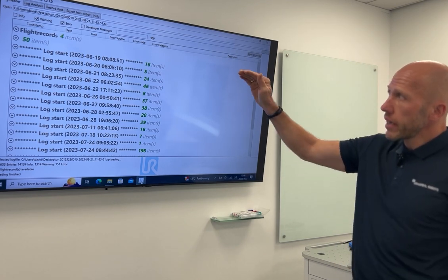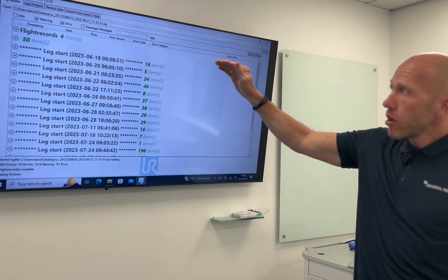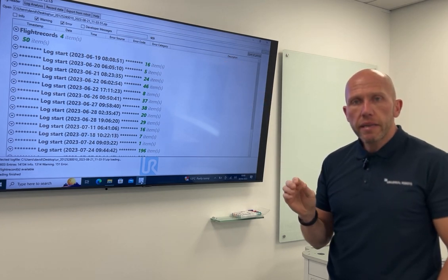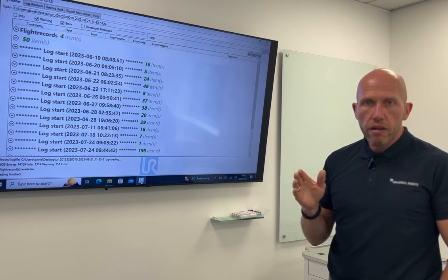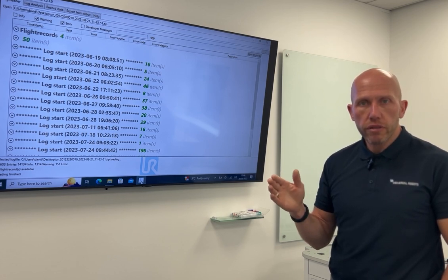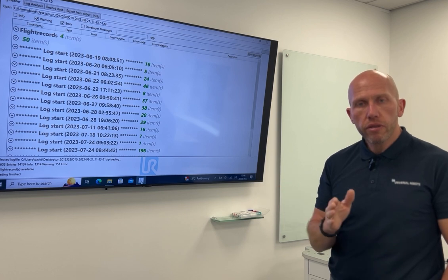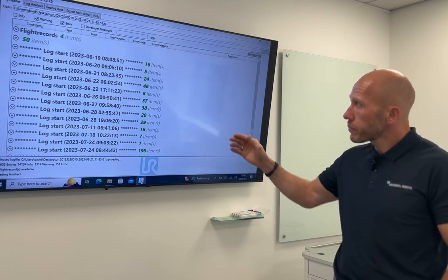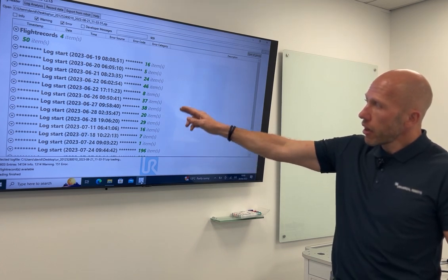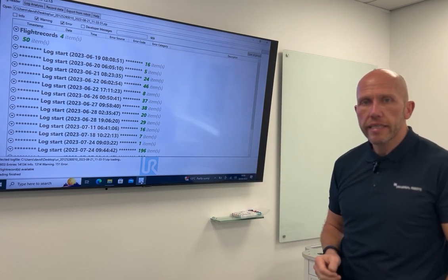The first thing we've got is the flight reports at the top, which are snippets of information that preceded the fault. It's of course nice to know what the fault was that caused the robot to stop, but it's also good to see what happened just before that incident as well. And then we can see the log data, which is all time and date stamped.